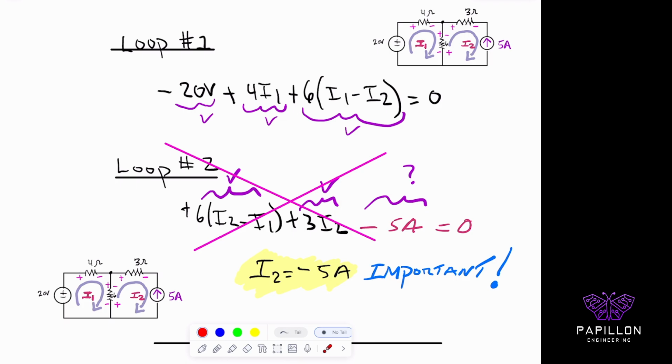The second thing is that it's minus 5 amps. Why? Because again, I'm assuming my direction to be positive, always clockwise. I'll put it here, I'll write it out. So again, here's my drawing. Anytime I go clockwise, my clockwise is going to be assigned the positive value. I'm going to put here CLK, which means clockwise for me. So if I assign that to be clockwise, and as I go clockwise, 5 amps is opposing my perceived direction, then I'm reading that 5 amps as not being positive. It'd be positive if the arrow were facing down, because it's going upwards. It's actually read as minus 5 amps.